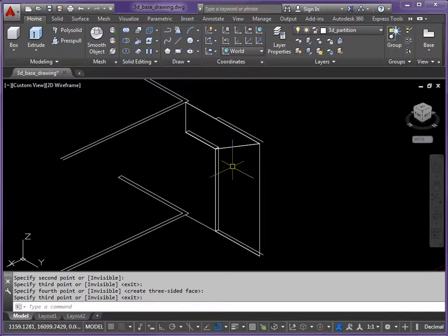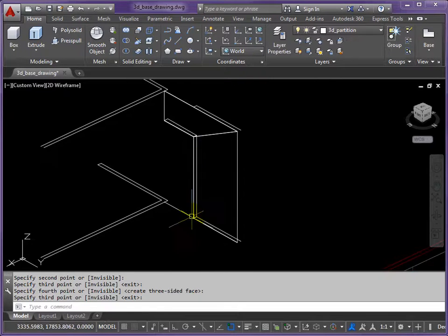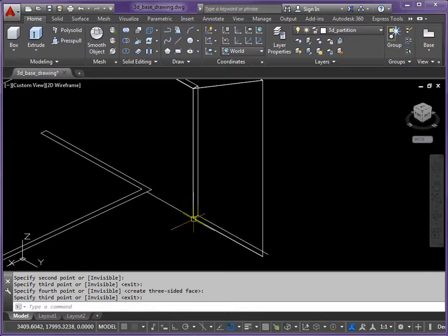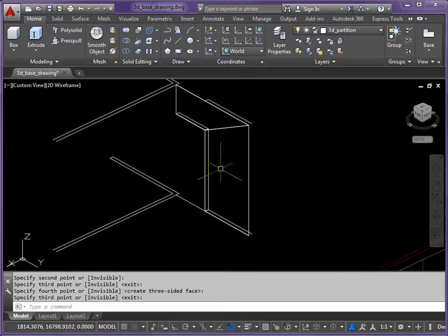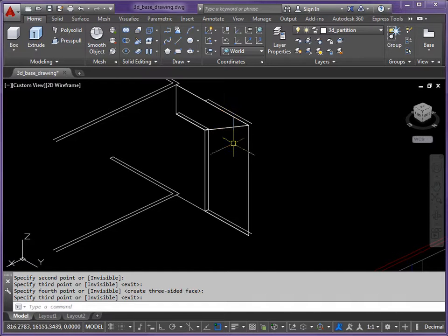The reason for doing these types of shapes is so that the surfaces share the vertices. At this point here, there's 4 3D faces sharing that vertex. Where these 2 faces meet, they share a corner as well. You notice that whenever they meet up with another 3D face, they're sharing corners. And what happens here is that it will weld these surfaces together better.